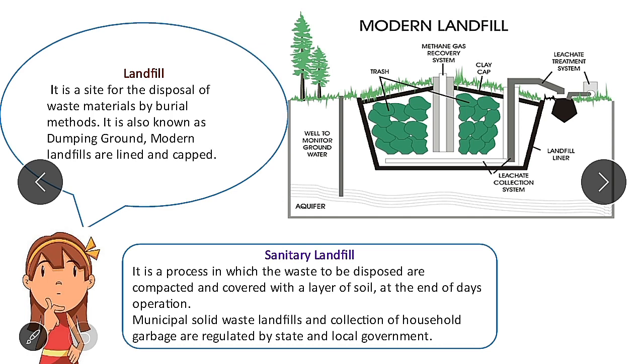This modern landfill pictorial representation is given here. You can see the well-monitored groundwater pipeline, and the trash is deposited in that particular pit, and methane gas recovery systems are provided as well. The leachate treatment systems and landfill liners are provided, and the clay cap is also provided, just to prevent the entry of waste gases into the environment or the groundwater. Whatever the contaminants are, they should not come into contact with the groundwater flow. To prevent that, they provide many protective measures.